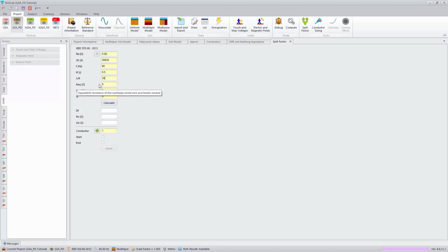In this instance, we're going to follow the tutorial, assuming we have 2 transmission lines with shield wires and 2 distribution lines with neutrals. We can expect an impedance of 0.455 ohms for our resistance and our reactance of 0.24. Hitting calculate, we can see our actual grounding system will be experiencing approximately 25,000 amps, producing a ground potential rise of our system.